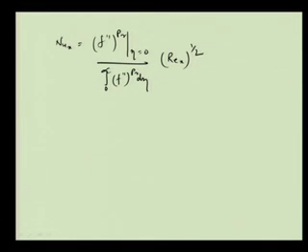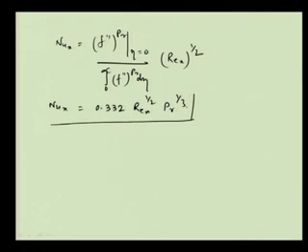Now, the numerical value has been computed, and it has been found that Nux is equal to 0.332 Rex to the power half and Prandtl to the power 1/3. So, just by computing the values of this part, it has been found that the Nusselt number can be found as 0.332 into Reynolds to the power half and Prandtl to the power 1/3. Okay. And this is obtained after just computing the values of this integral.